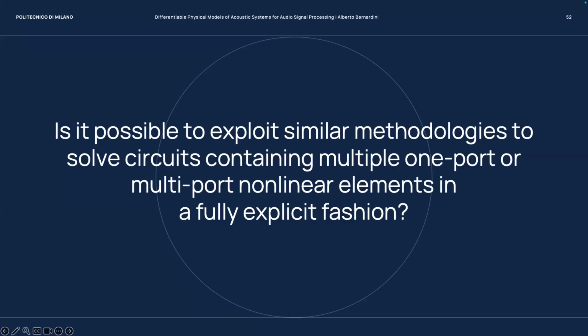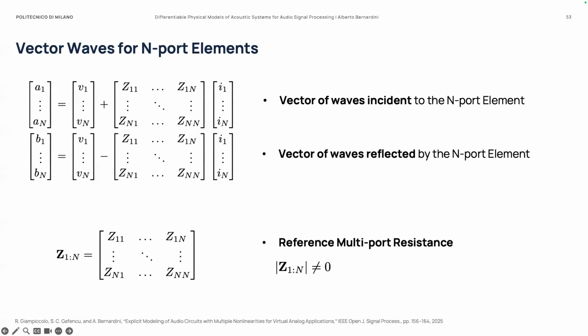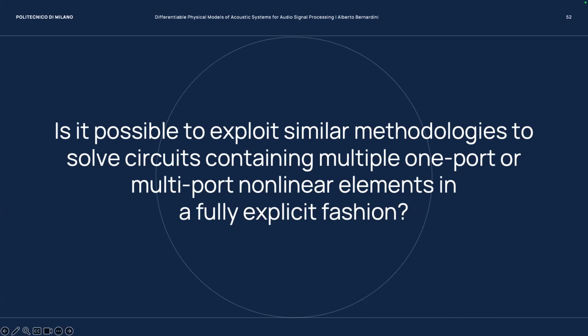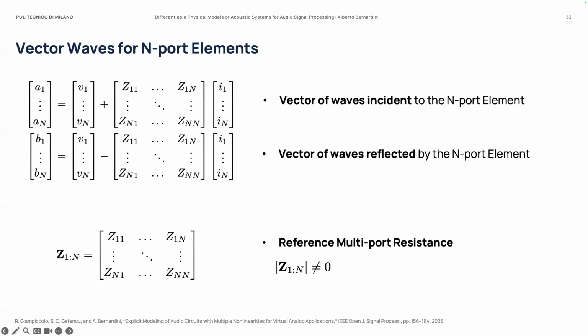So now we try to push this approach forward again, asking ourselves: is it possible to exploit similar methodologies to solve circuits containing multiple nonlinear elements in a fully explicit fashion? So the idea is that our block might contain multiple nonlinearities. So far, it was one one-port nonlinearity or one multi-port nonlinearity. What if I collect all the nonlinearities in one single block?